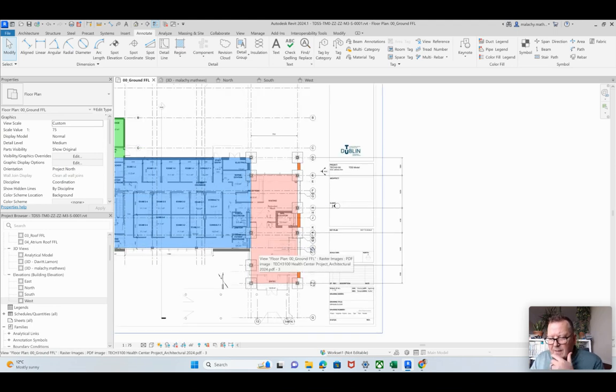All right. Now, next thing that we need to do is put in the roof. So I'm going to be putting in a roof that will be coming out. It'll be on that grid line or just in front of that grid line up around here. I'm going to extend it out there. I'm going to put an overhang of about 1500 mil, 1.5 meters out around on this side, and not so much on that side there.